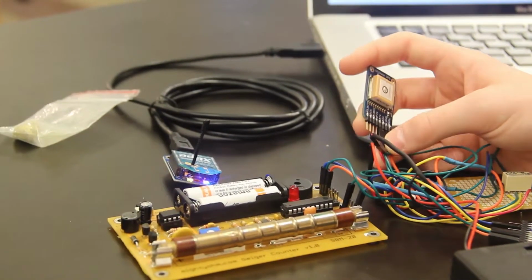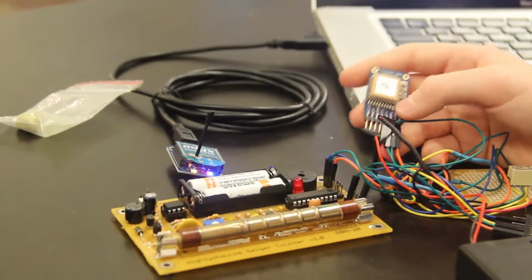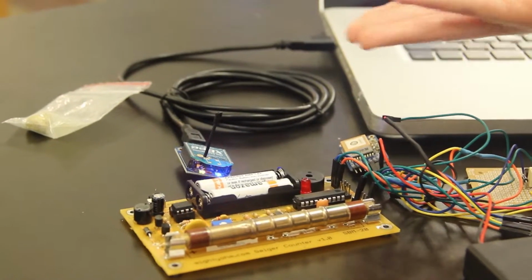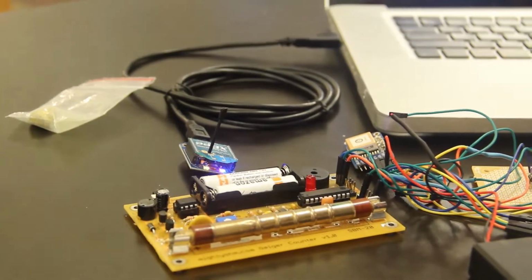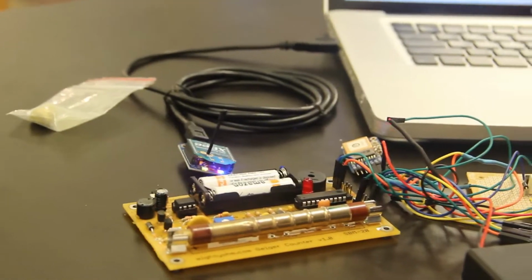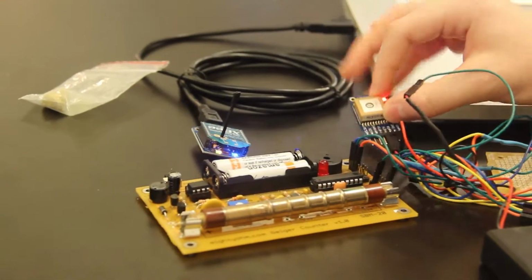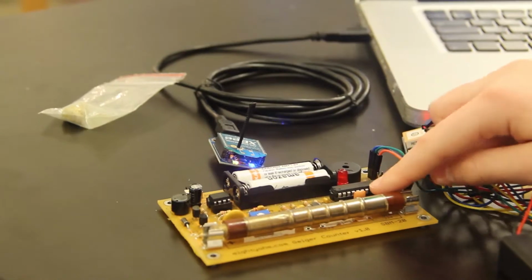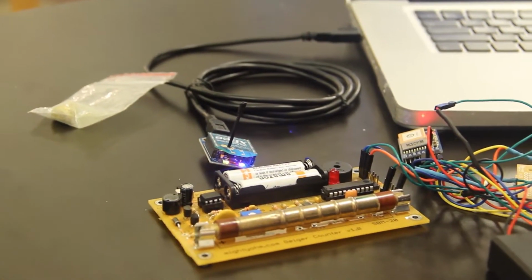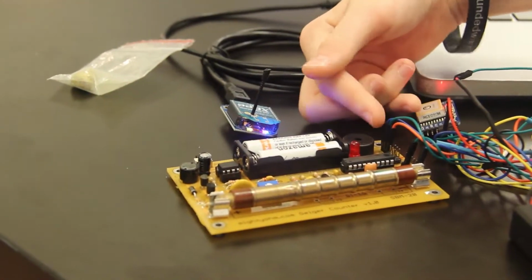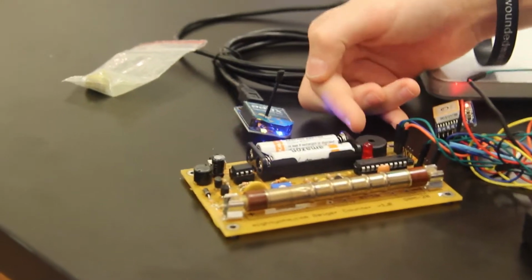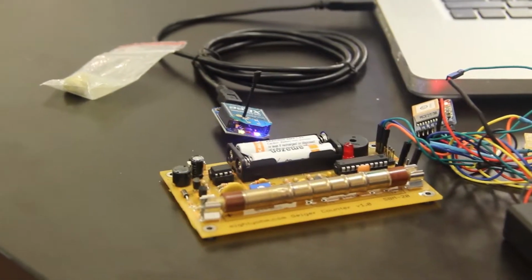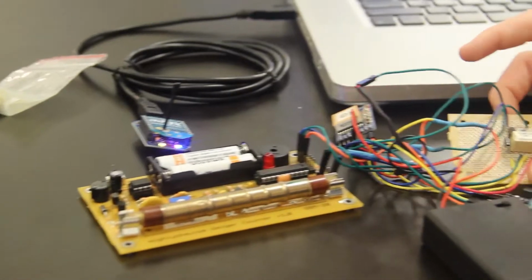This was fairly difficult to connect because at first I wanted it to output both Geiger counter and GPS data as a single string, but in connecting the GPS up to the ATtiny, I realized that this chip had limitations in terms of the amount of RAM that it had, so I had to think of another solution,